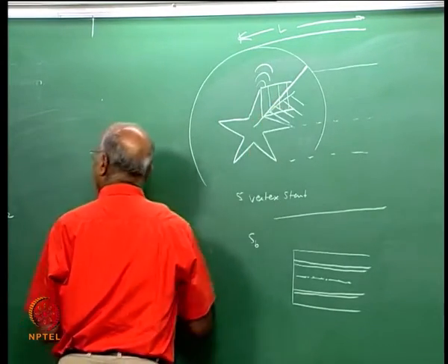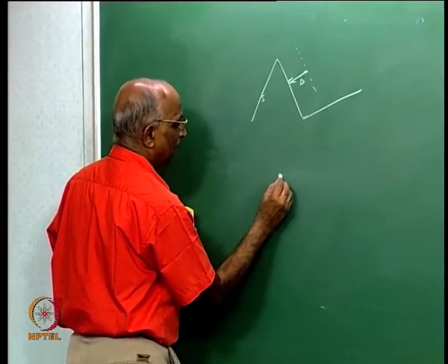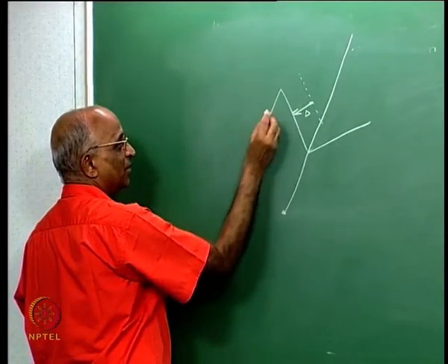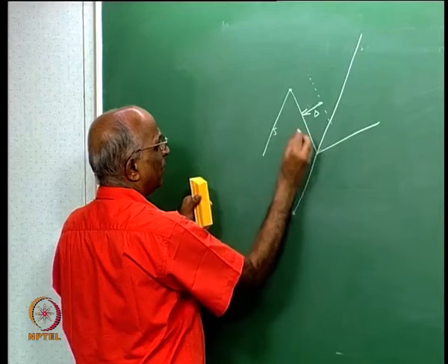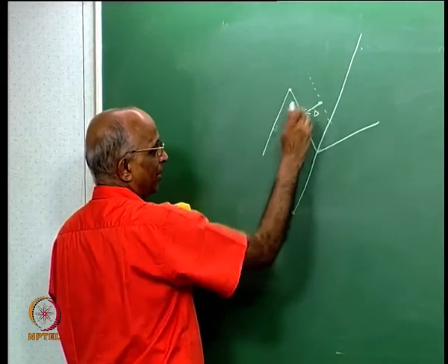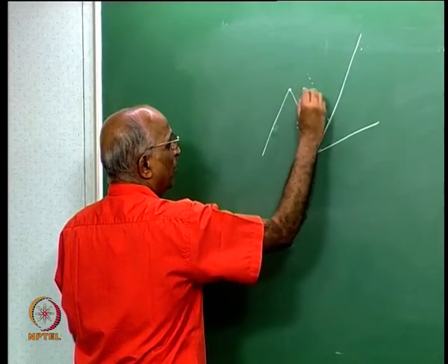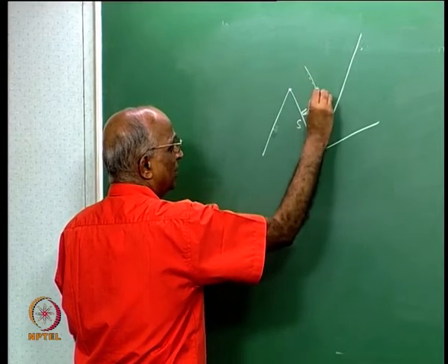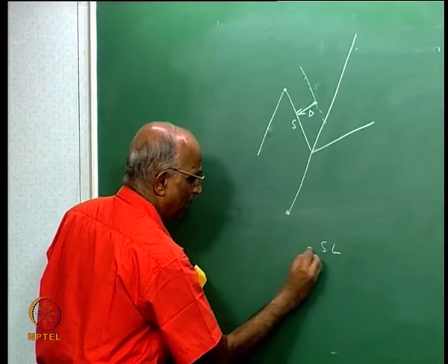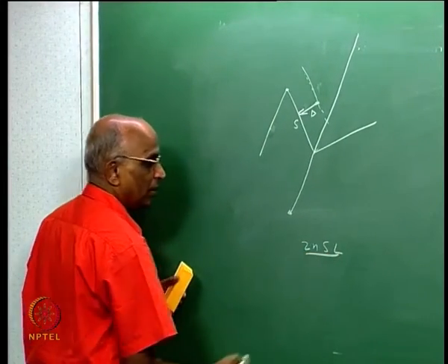And now with this axis of symmetry I can tell myself, well, my center is over here, this side and this side are symmetrical, therefore if I can calculate for this single surface S over here how it is going to change the value of S, when the grain moves maybe by a distance delta, if I can calculate the new value of S1, let us say, or the new value of S, then I can say S into L into, now I have 2n of these surfaces, 2n SL will be my burning surface area.